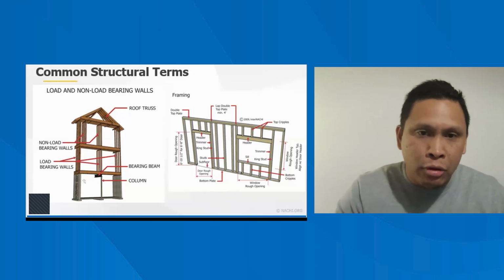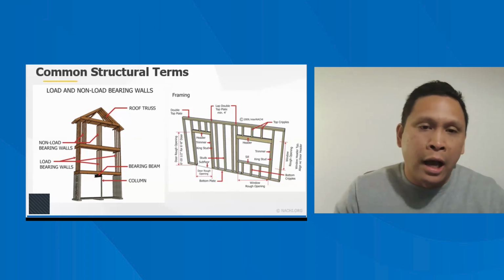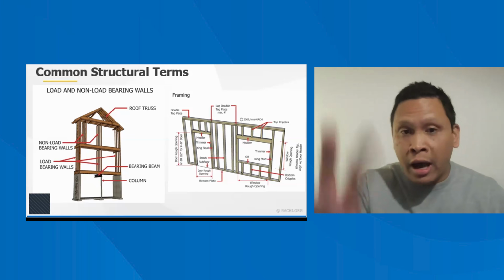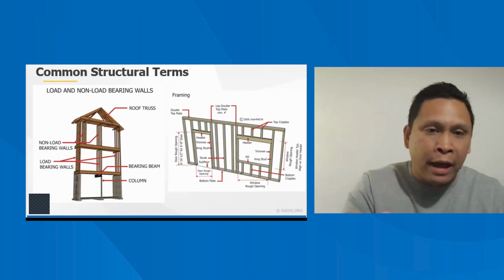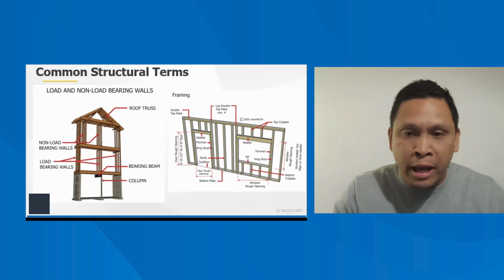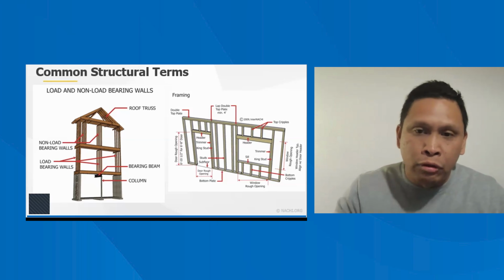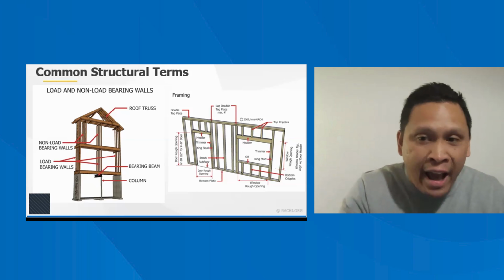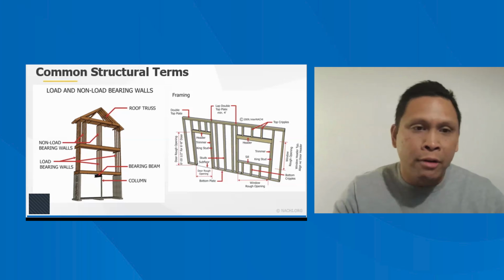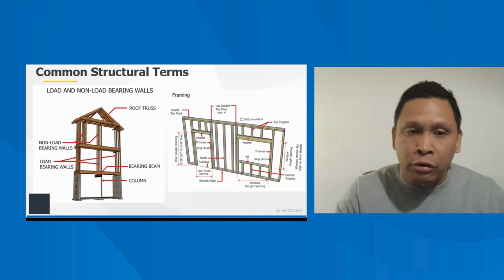that flooring system there. You can see here the whole entire system is being supported with masonry columns. Masonry columns, vertical compression members, right? The height of that column has to exceed three times its thickness in order to be able to do its job, and whose width is less than one and a half times its thickness. So a column could be narrow, it could be slender. It's going to be a vertical compression member.